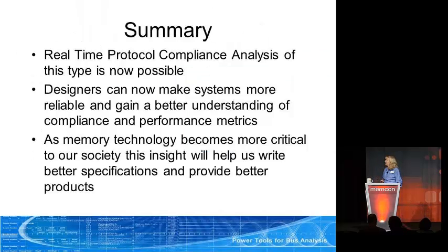So to summarize, real-time protocol compliance analysis is now possible. And as Jenny reviewed, the difference between this tool and some of the other tools that you see is that a lot of the tools will grab a large amount of trace memory and sift through it and look for violations. We liken that to emptying San Francisco Bay with a bucket. Not the right tool for the job. You're going to be there for a long time with that bucket emptying San Francisco Bay. The real-time tools with real-time counters look at every single clock tick. Nothing is missed. So you're going to get to the source of your problem a lot faster.